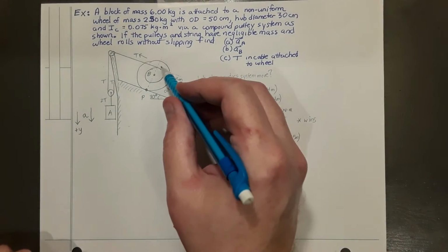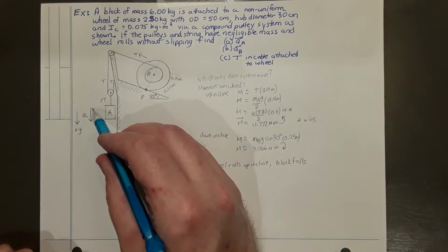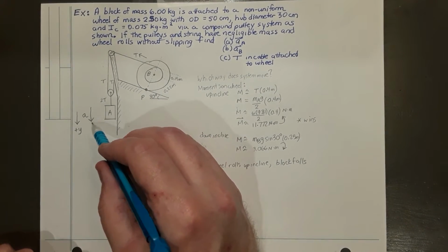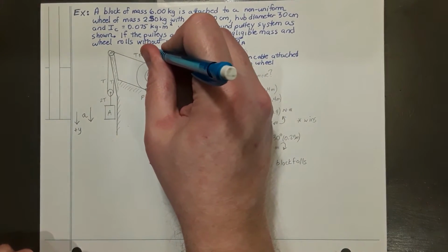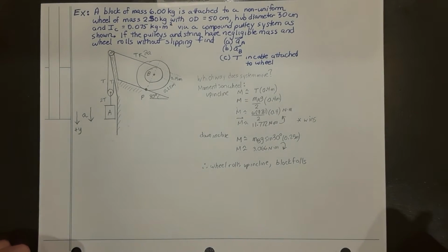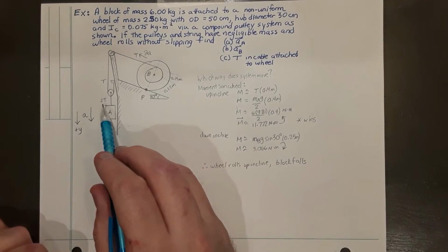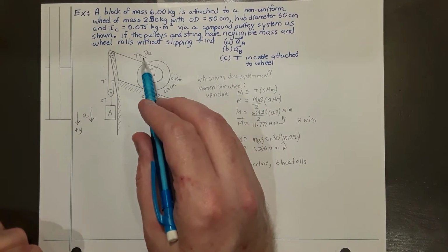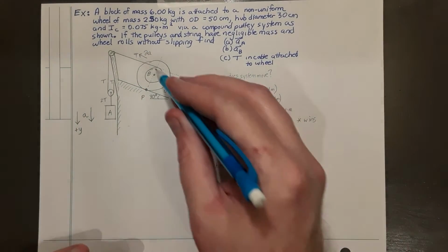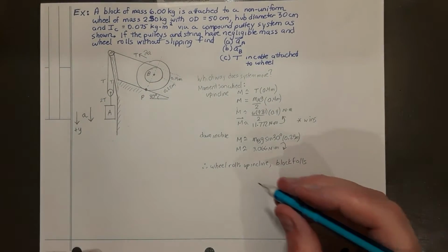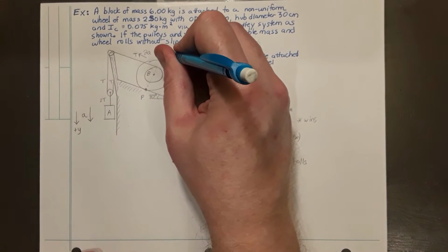The cable is going to be accelerating up the incline, but because of the mechanical advantage, if we get one displacement, velocity, or acceleration output on this side, we must have two acceleration, velocity, or displacement in order to maintain conservation of energy. Basically, two tensions times one displacement has to equal one tension times two displacements. And so the linear terms are double on this side of the compound pulley system. So therefore, I'm going to choose the following